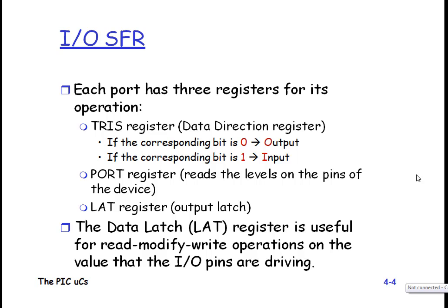Port registers read the level on the pins of the device. The latch registers are output latches. Latches hold digital data in the form of 0 and 1, which is stored in them. The data latch register is useful for read-modify-write operations, and read operations on the value of input pins